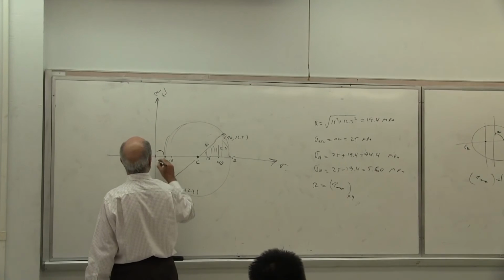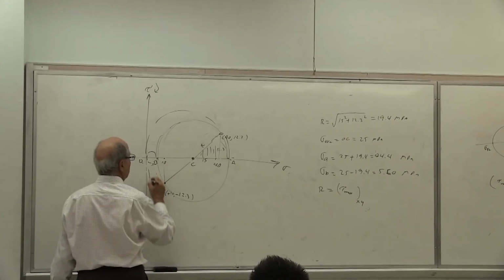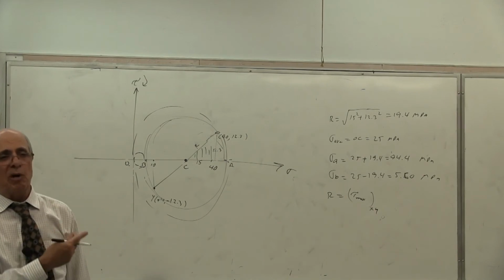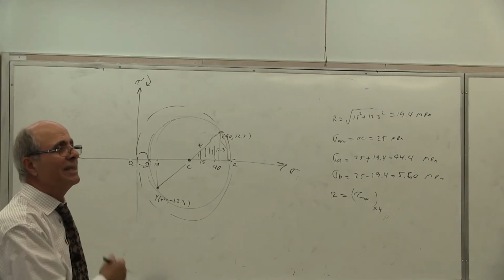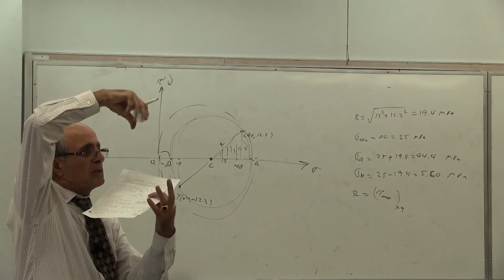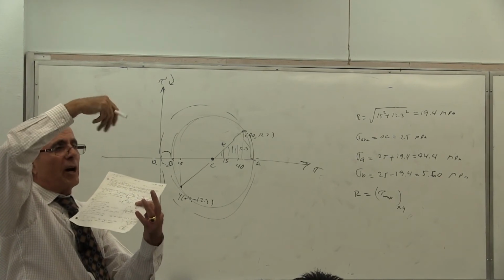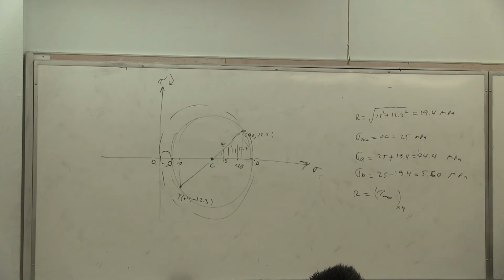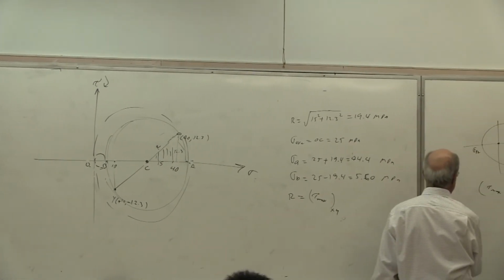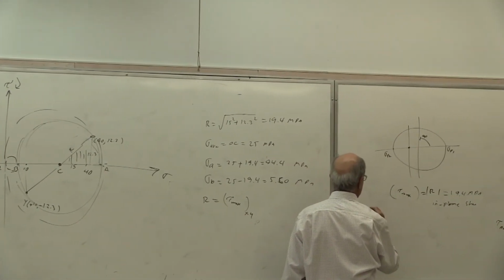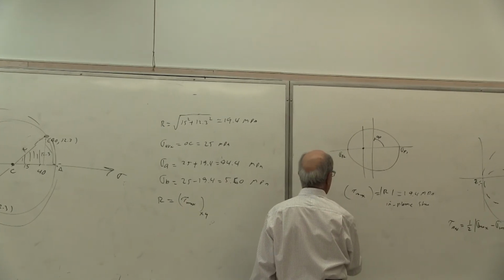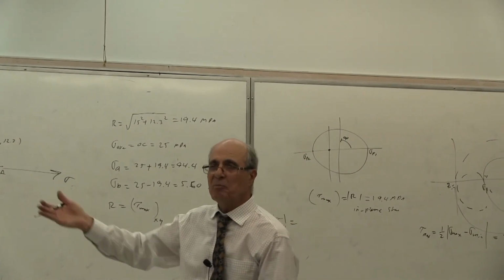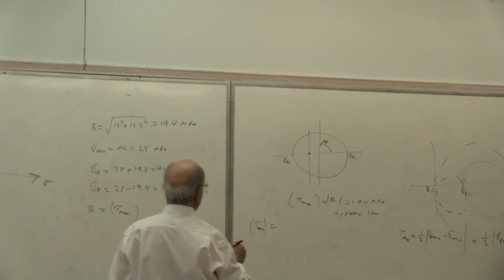So when you draw the two circles or three circles, one of them becomes the largest one. For this problem, the one that becomes largest is x and z. So the rotation is about which one? It is about the y-axis. But what is tau this time? Tau max is still sitting here. Use that one. Tau max, which is in which plane now? This is very important. It's not in the xy plane. It is in the xz plane, because you said it's rotation about the y-axis.